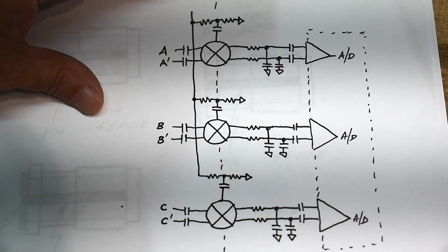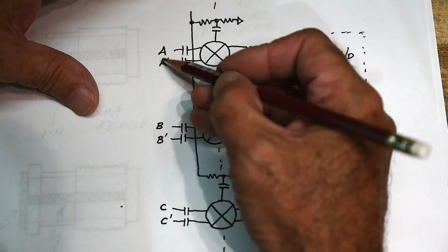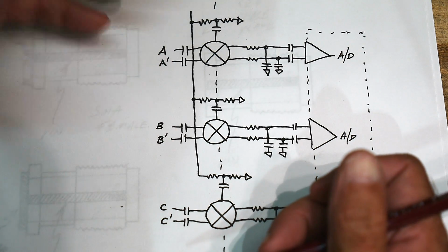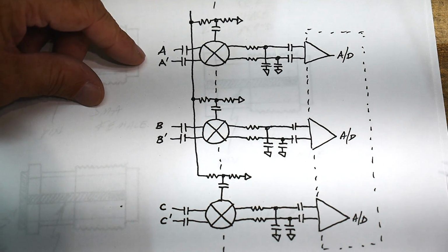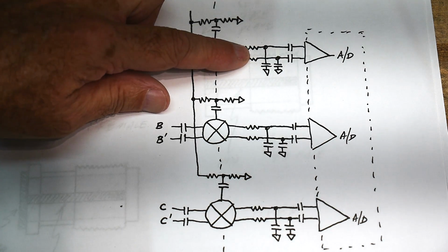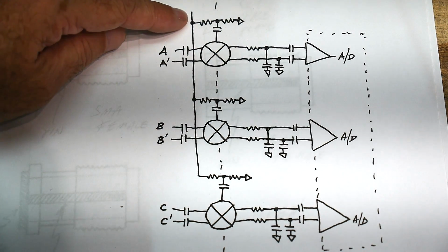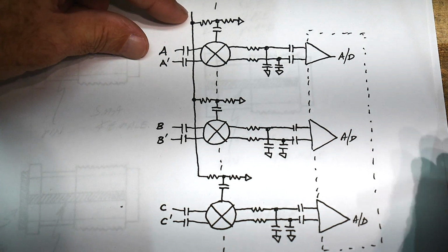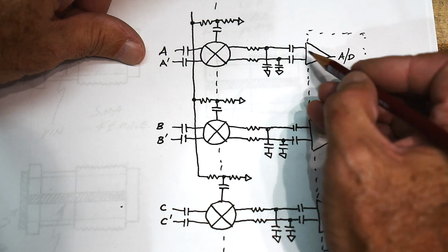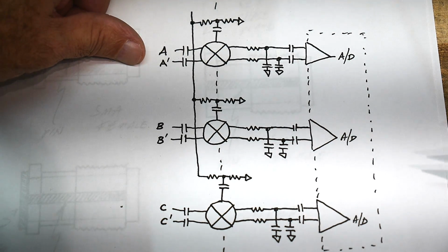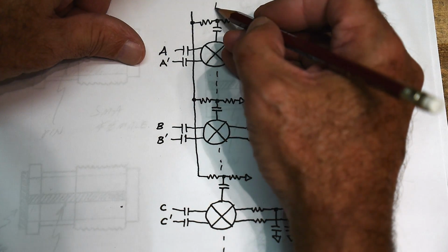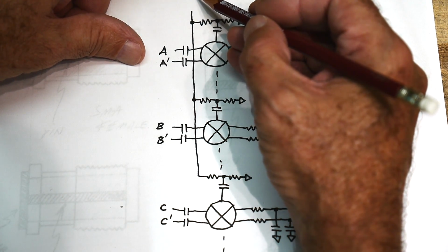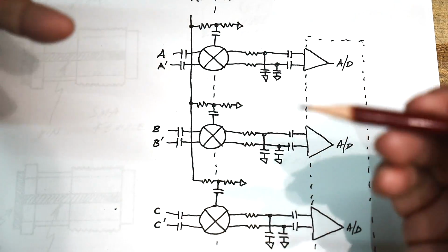But his idea was, let's go ahead and take those things we want to measure, A prime, B prime, C prime. So these are differential pairs here. And we want to measure these 3 things, but they're too high in frequency. So every RF engineer knows, well, if it's too high in frequency, you can always put it through a mixer and make it a lower frequency. So that's what this does here. There's 1 master clock, and it comes in, and it runs through these 3 mixers, and it takes whatever you have, let's say it's 1 gigahertz, and it's going to mix it with something, and it's going to end up at audio frequency. So let's say 10 kilohertz is a good frequency for you. So you have 1 gigahertz plus 10 kilohertz, and when you mix it with 1 gigahertz, it mixes down to 10 kilohertz, right?